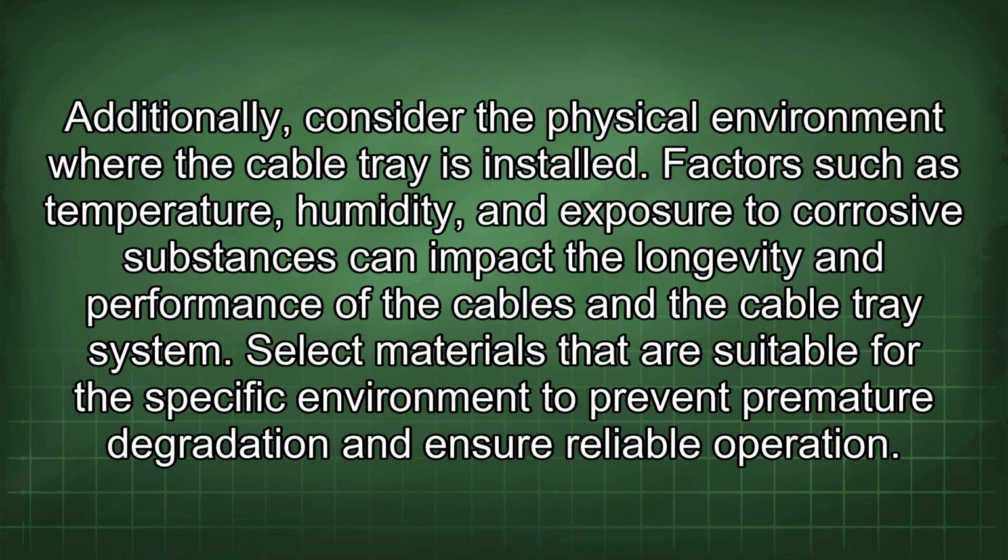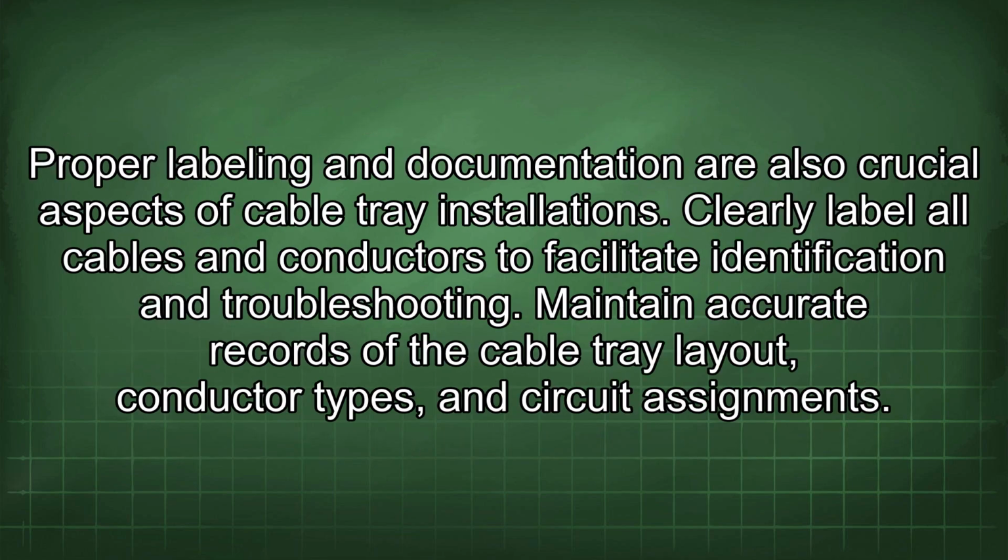Additionally, consider the physical environment where the cable tray is installed. Factors such as temperature, humidity, and exposure to corrosive substances can impact the longevity and performance of the cables and the cable tray system. Select materials that are suitable for the specific environment to prevent premature degradation and ensure reliable operation.